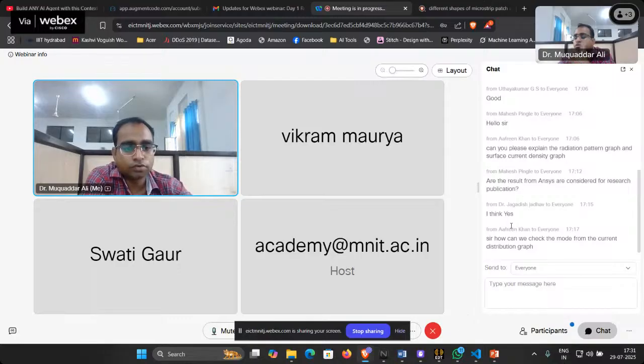But right now you do this from there. Once you have finalized the design, go to CST, import this design, you can export from HFSS in 3D, then import that design directly there and attach a wave port or whatever port you want, then simulate it. If both the results are consistent, then only go for fabrication. Okay.